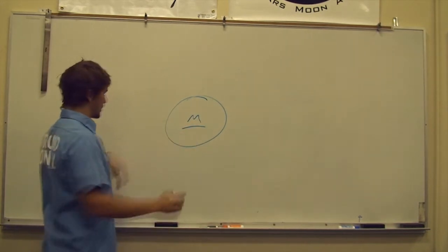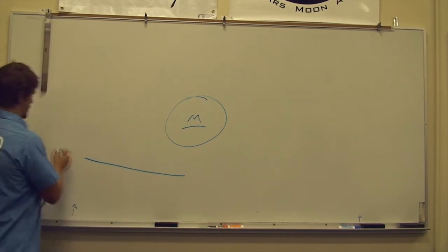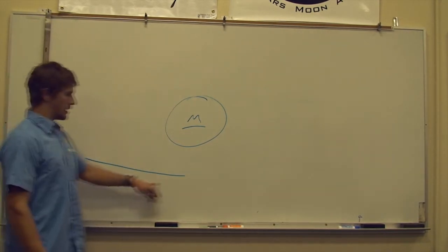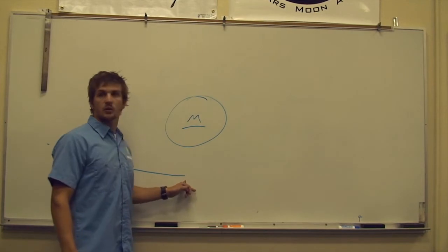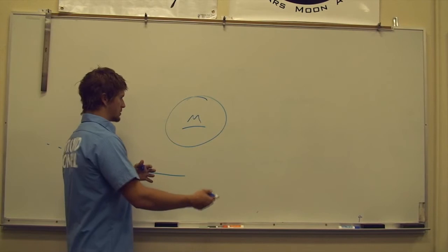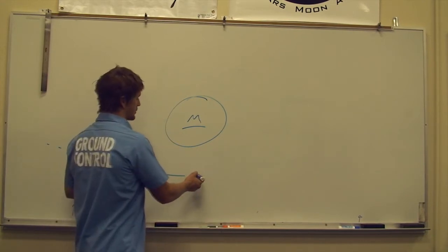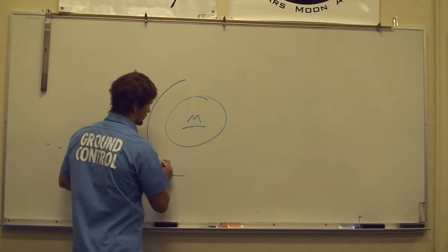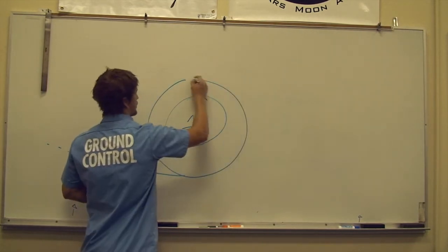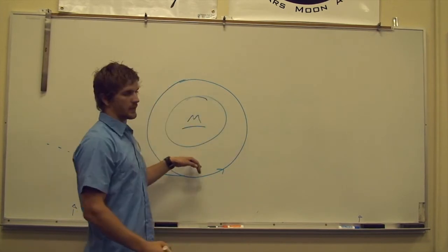And so we will come into the moon on our translunar injection, coming from all the way over here, and we'll go ahead and perform our lunar orbit insertion, which is essentially a retrograde burn, which means we're firing against the direction that we're going. And that is going to slow us down into this parking orbit going around the moon.